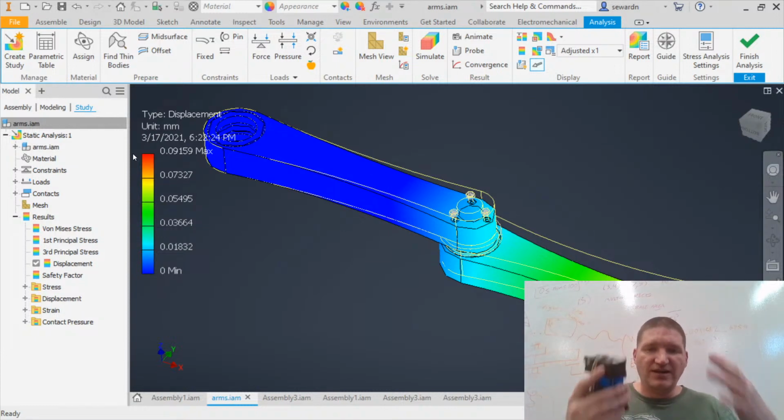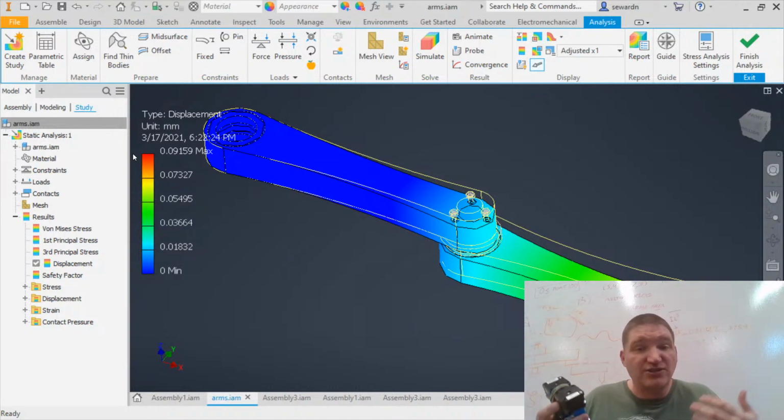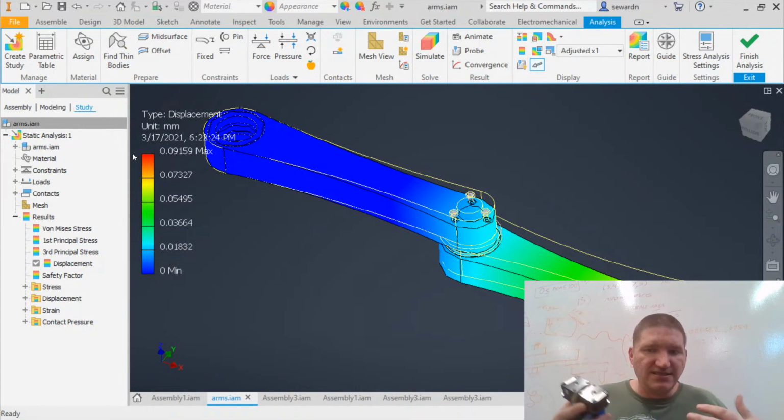And remember, whenever I have the arms together, gravity is going to load things consistently. So if they sag, they sag. As long as I get consistent precision, I can use mesh bed leveling and stuff like this to hide some of my sins. So I'm not too worried here.